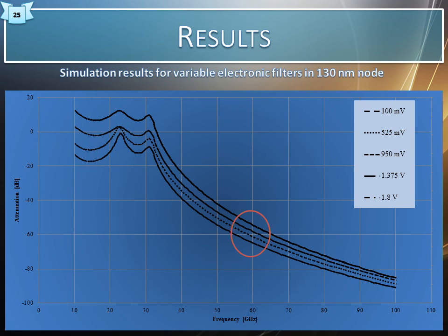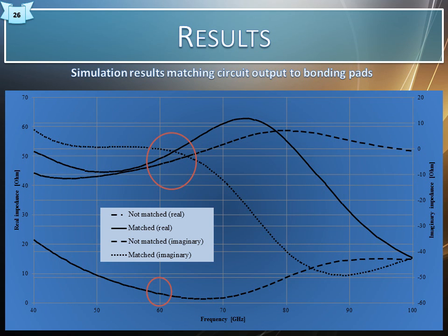These simulation results show that it is possible to change the attenuation in a passive circuit through a DC-controlled active component, which is a common-base transistor amplifier keeping optimal gain bandwidth product. The amount of change is approximately 6 to 8 dB in simulations, where measured results have different limitations, such as parasitics, equipment, and layout constraints, and will become evident in the presented measurement results.